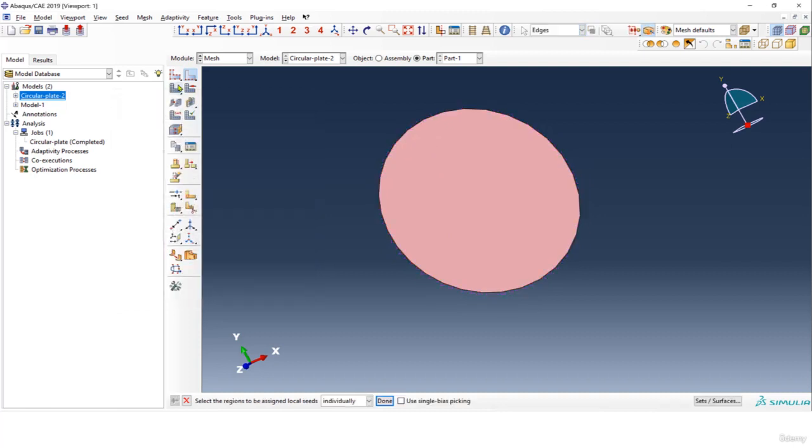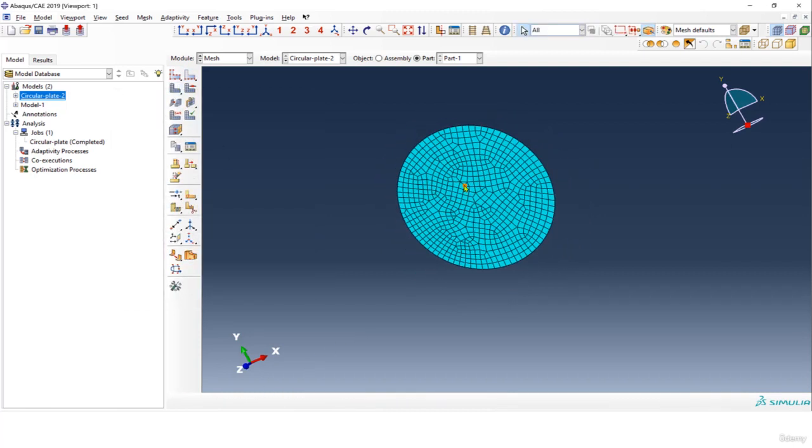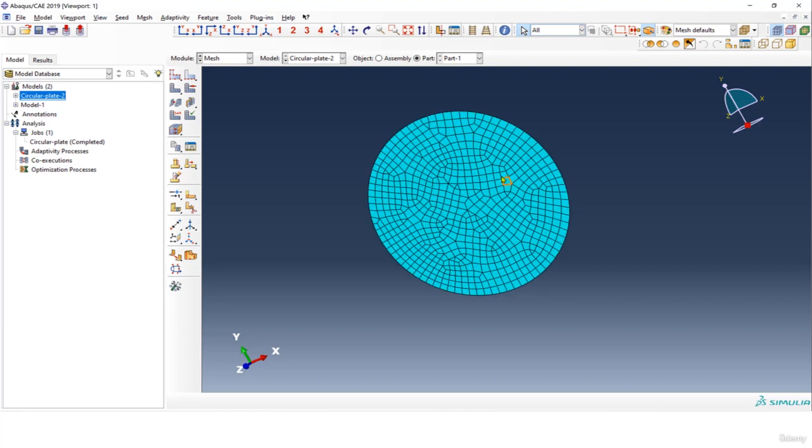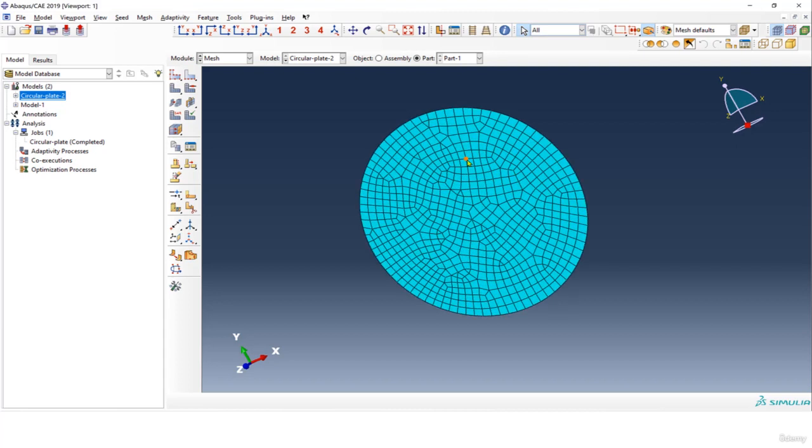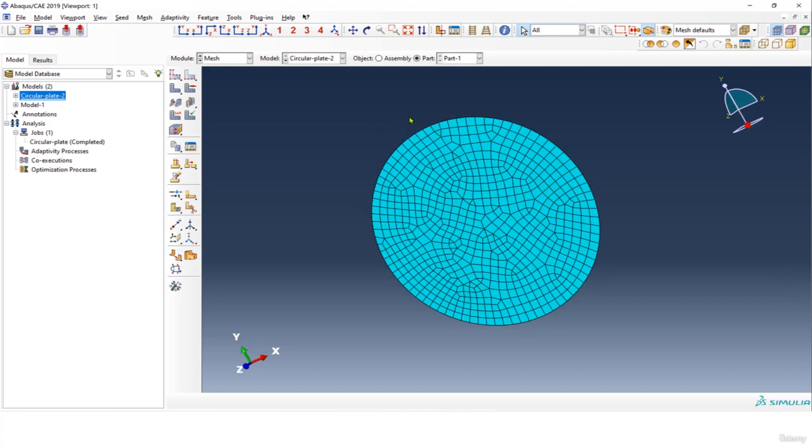We can assign this one, run a simulation, and if the result is not close to our hand calculation, then we can come back here and play with the mesh a little bit more. But we don't really want to apply a too fine mesh and then just waste the time for solving it. So always start with the acceptable, not too coarse, not too fine, in the middle, and then later modify your mesh. Obviously for a complex geometry you always have to do a mesh study to make sure that your result is not going to change by changing a mesh size. This is very, very important.